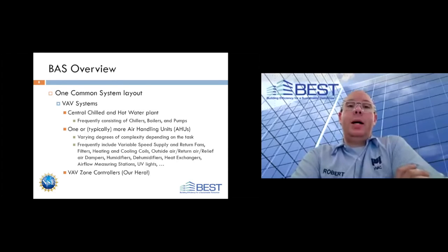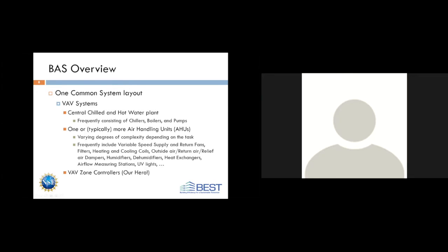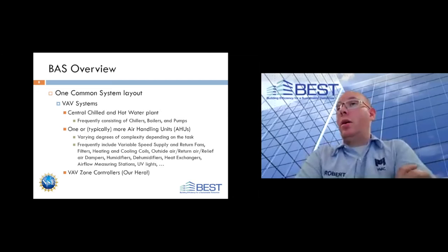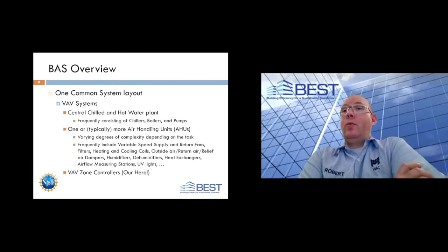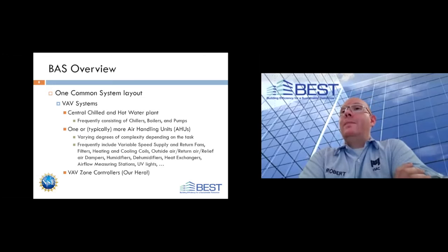We also have heating and cooling coils. These are what utilize our hot water and chilled water, or our steam, whatever our building is producing, to increase or decrease the amount of heat in the air that we're circulating throughout the building. Now, typically in a variable air volume system, we try and distribute cold air or cool air as our standard. Something around 55 degrees to 65 degrees, depending on the outside air climate, heat load in the building, et cetera, et cetera.